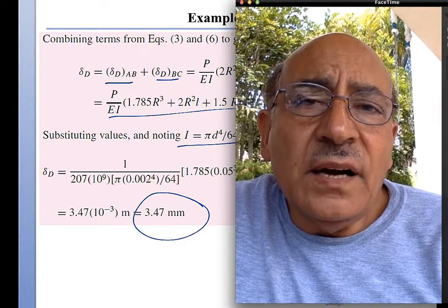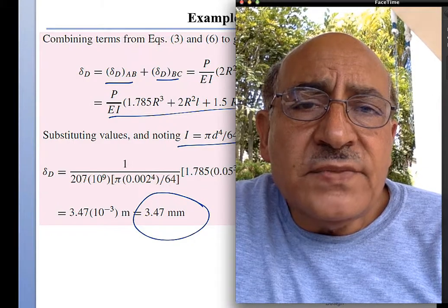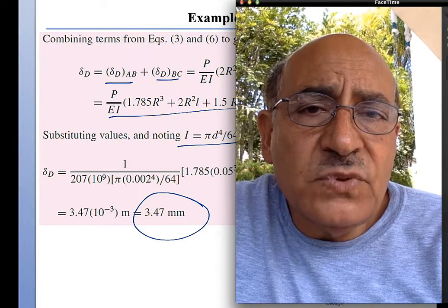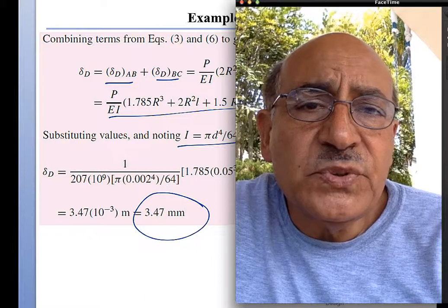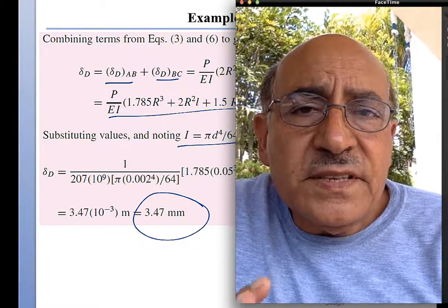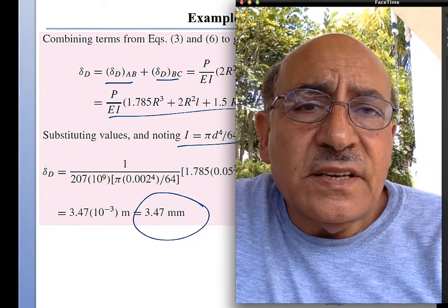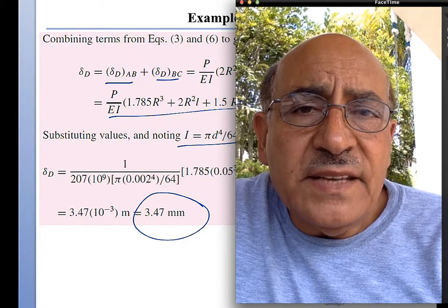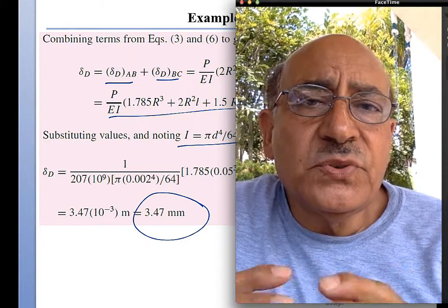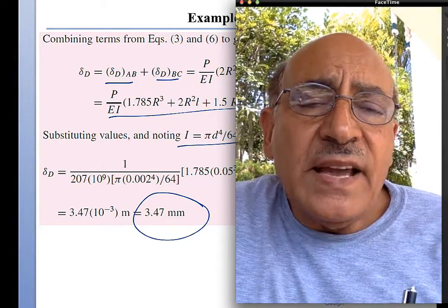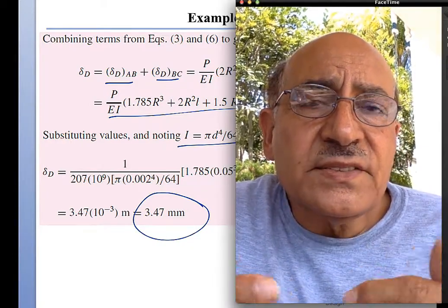Or if the beam is hinged at some point where it cannot move, or even if it moves, we can compute the displacement from some other means. In all of these kinds of situations, the most direct way is to use Castigliano's theorem, and compute the deflection, including the redundant reaction, redundant like the unknown, the extra unknown.